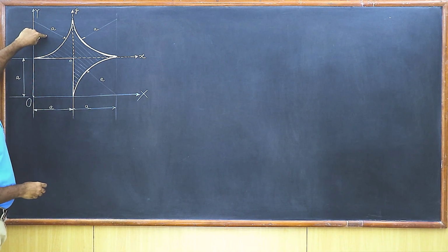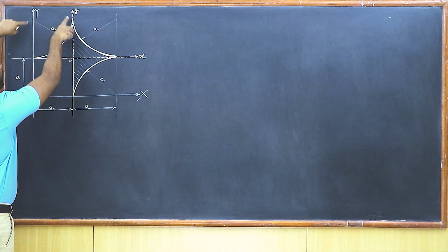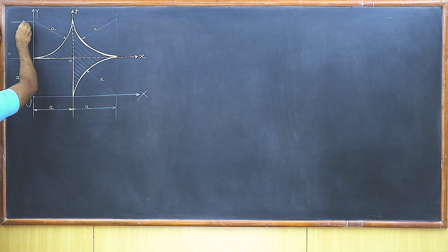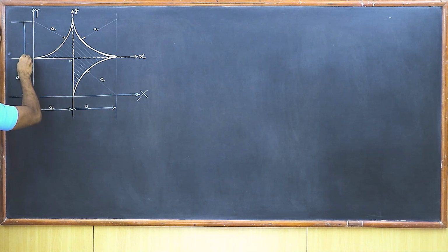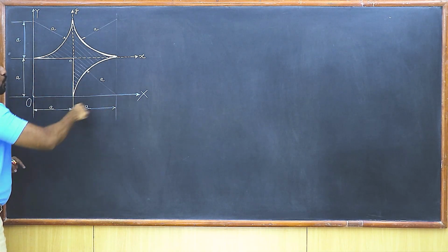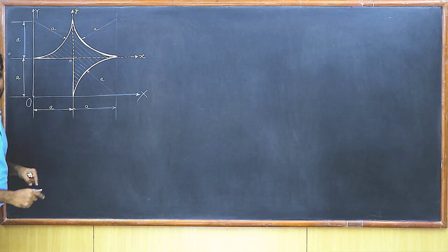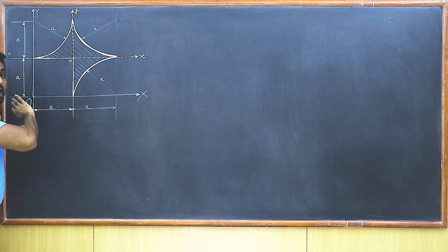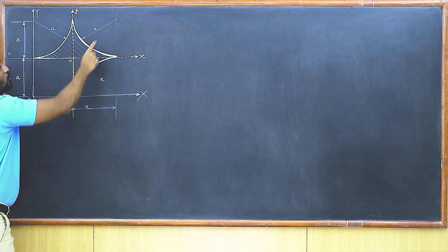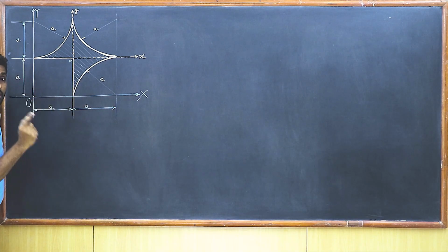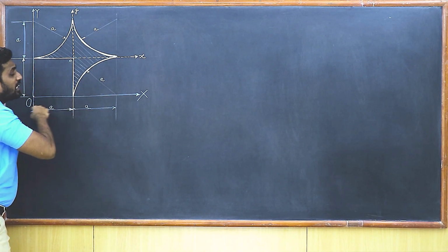Whereas you can observe here also there is a quarter circle. It is again removed from a square plate, isn't it? So that's radius a, that's radius a. So this length is also going to be small a. So the total length becomes 2a here. This length also becomes 2a. So this is a square. From this very big square, I'm going to remove 3 quarter circles. 1, 2 and 3. The 3 quarter circles need to be removed. So the areas of the 3 quarter circles are going to be negative, and the area of the big square is going to be positive.